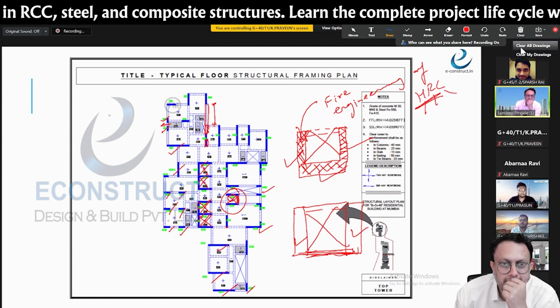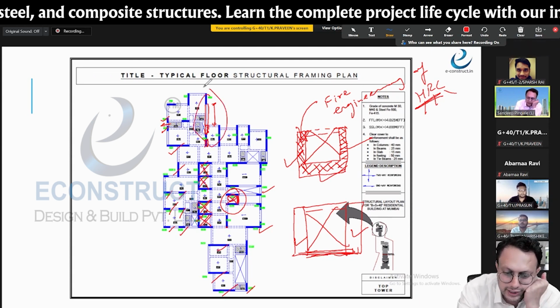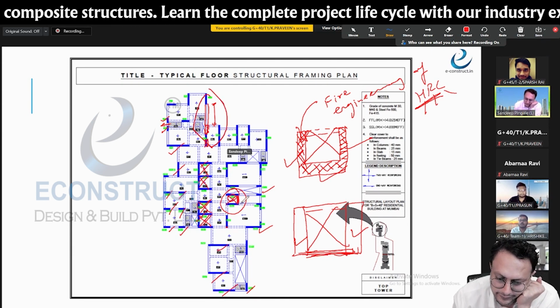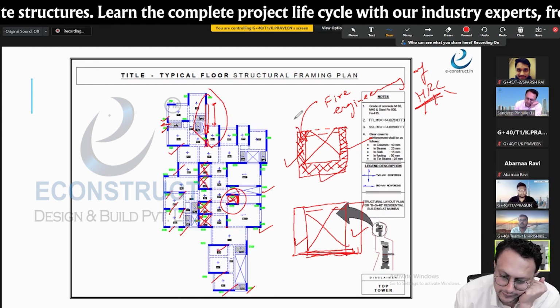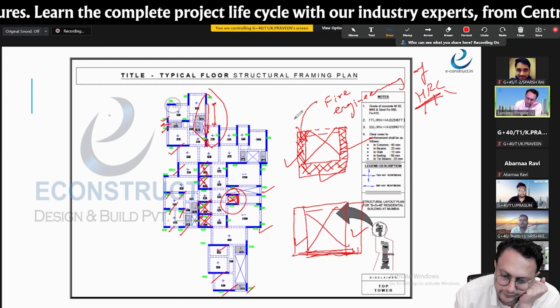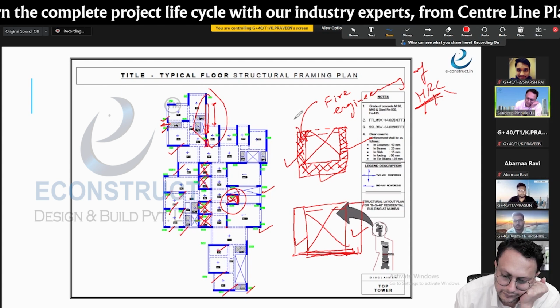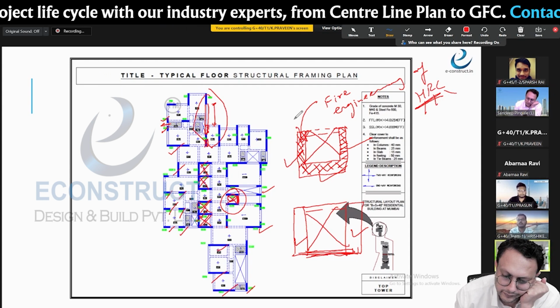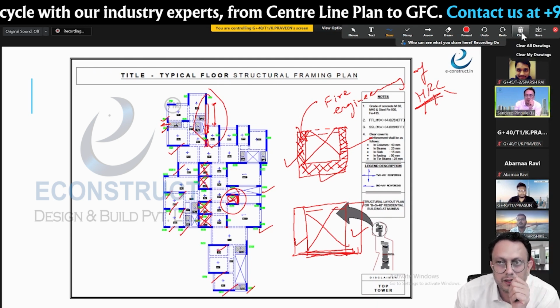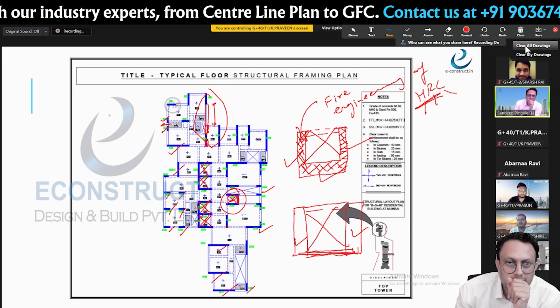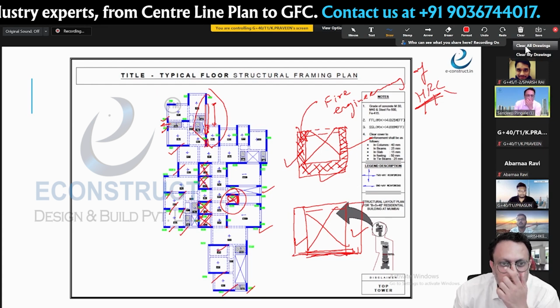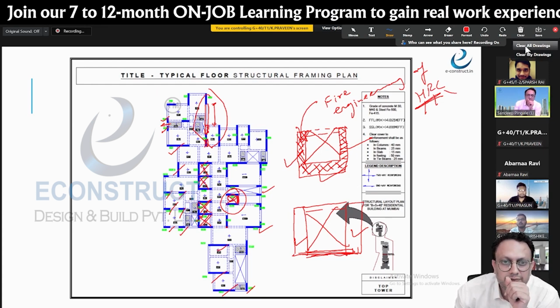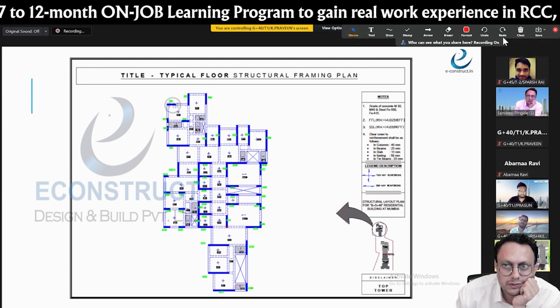The rest, I think it is okay. Only one change over here, I guess. So there is the parking, sir. So say if you provide the shear wall, then parking will be disturbed. Is it? Okay. Yes, sir. Okay, then we need to design that as a deep beam. Just check the span and other things. Better. Yes. Okay, sir.